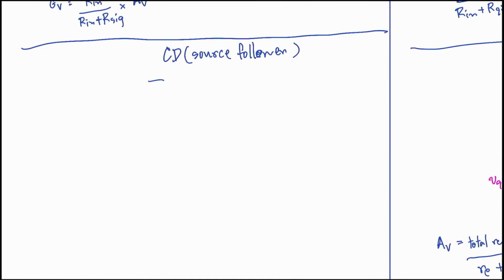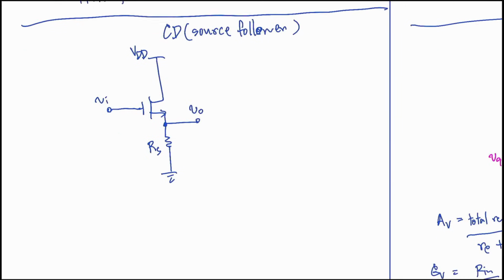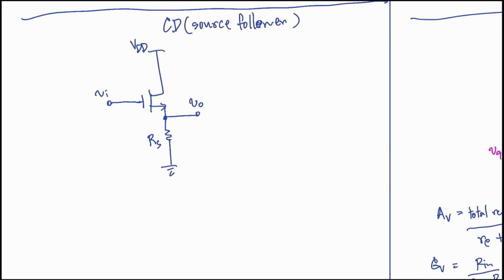The circuit diagram will look similar to each other. Oh, I am sorry, let me clarify that. Usually in this specific configuration, the drain does not actually have an RD resistor associated with it. Instead, there is an R source connected directly to the ground. We have an input signal coming in, and the output is taken directly from the source pin. So looking at the source terminal, that is where the signal path is actually being directed.